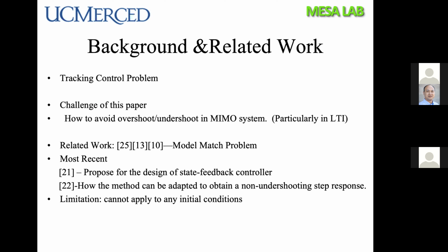A fundamental issue in classical feedback control is the design of control laws that provide good performance, both at steady state and during the transient. The steady state performance is typically assumed to be satisfactory if, once the transient is finished, the output of the system is constant and equal to the desired value.